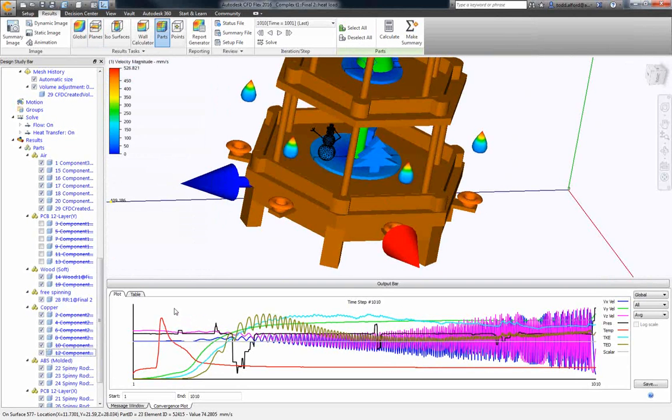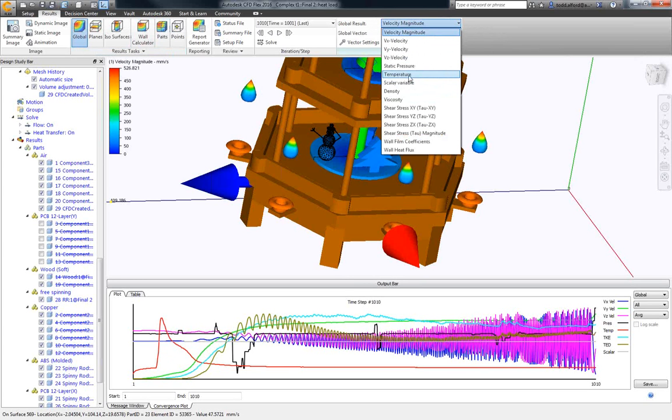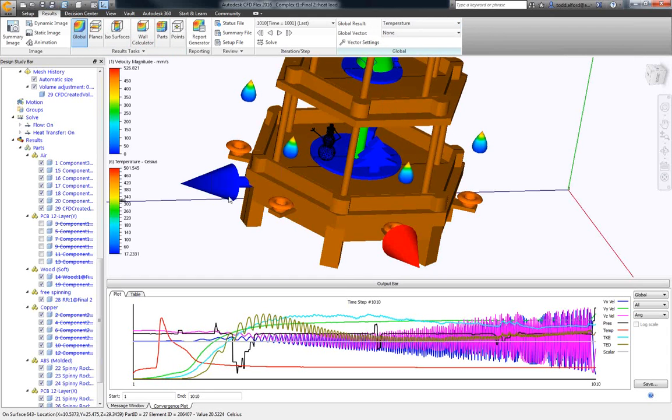One thing that I wanted to point out, because I got pinged on this by several people, is that the convergence plot here looks absolutely crazy. When you're doing natural convection, you usually get this bump up in the temperature because we're going to heat up the air locally at the flame. And I'm actually curious, I don't think I checked this. Let's check my temperature. Awesome. Look at that.